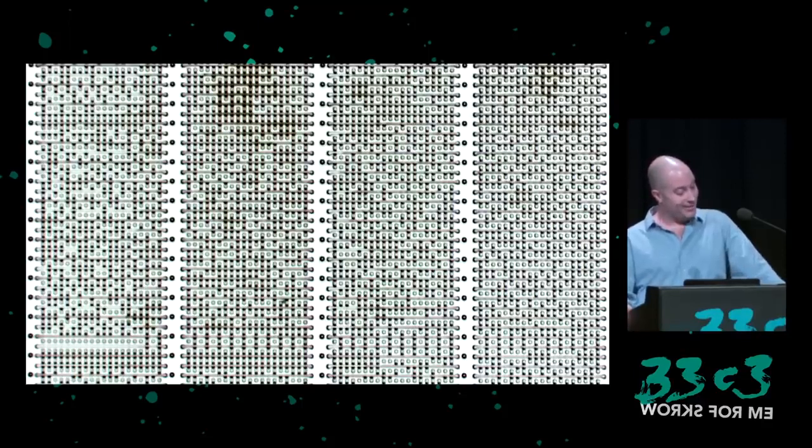Image quality is important. The better the photographs, the more consistently the bits will be visible. But it doesn't have to be really perfect. You can do some image processing on it. You can even repeat the process on multiple chips, delayer them and photograph them, and at some point you'll be able to have the entire ROM clean and consistently visible.